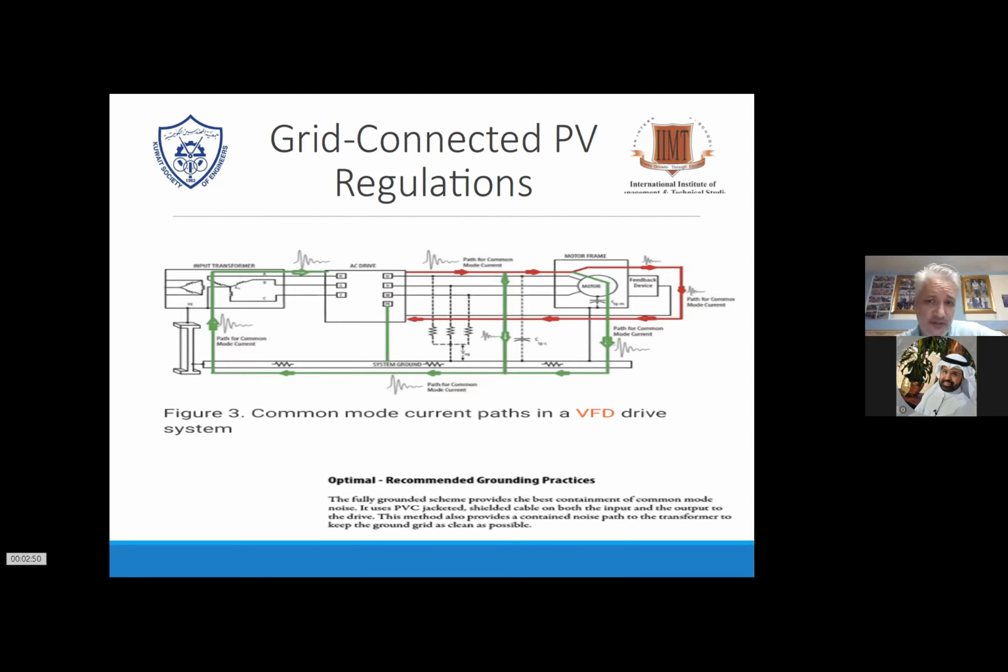With a 30 kilowatt system he had destroyed the whole installation, because he used only a 4-core cable and was not willing to run a separate wire. So I changed the bridges and put a 50-meter long 16 millimeter earth cable to the newly installed system, and then the system was running as on day one.